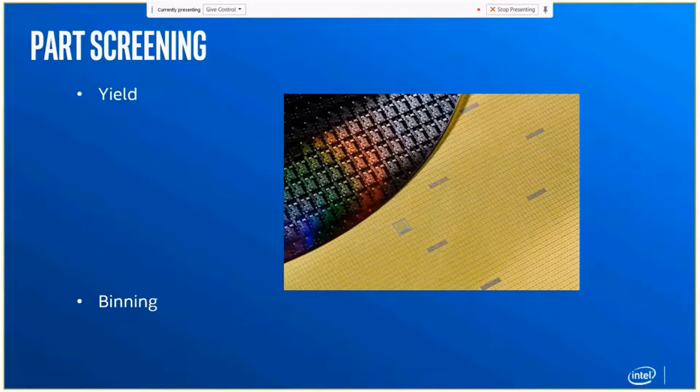One thing that we do is characterize how much current it leaks, right? If there is a lot of leakage current, it's going to take up too much power to run the device. Whereas if it has very little leakage current, meaning when it's not doing much, it's not leaking anything at all, fantastic. That's a good part, excellent part, right?